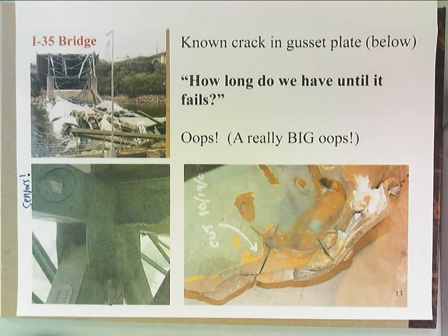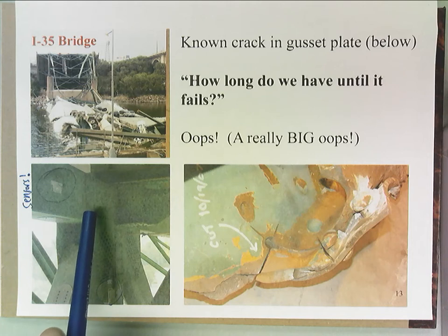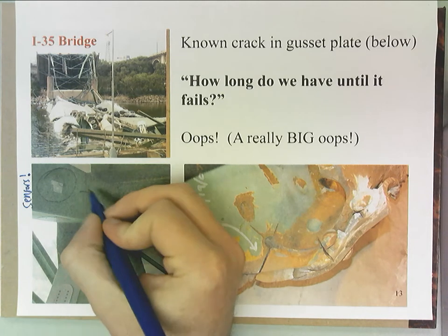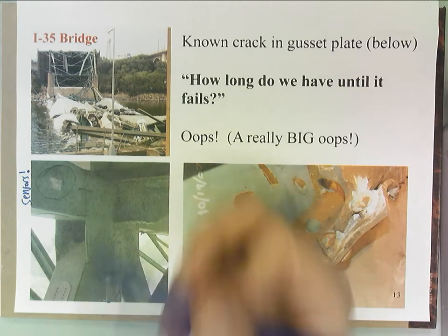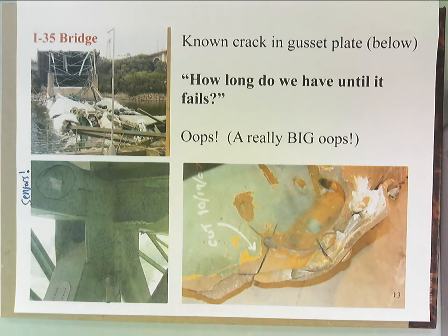We don't always know what all the operating conditions are. And so we'll take a design and we'll slap on a safety factor. Like, oh, hey, I need an I-beam that's this thick. Well, let's just double it. So you're taking your cross-sectional area, you're doubling it. Something like that, okay, for your factor of safety.